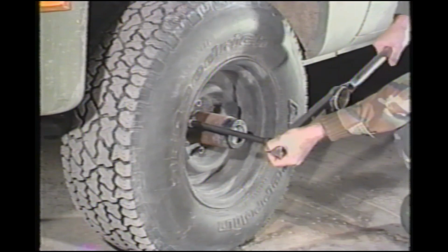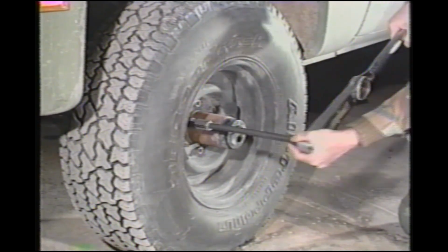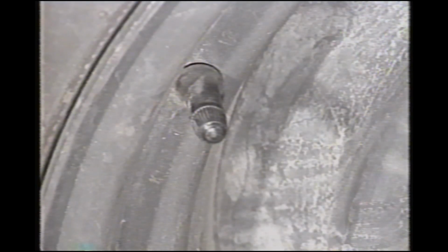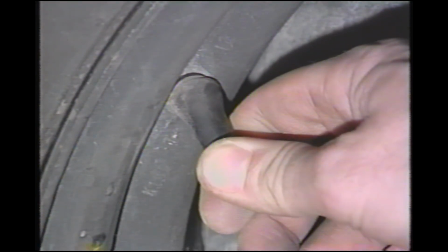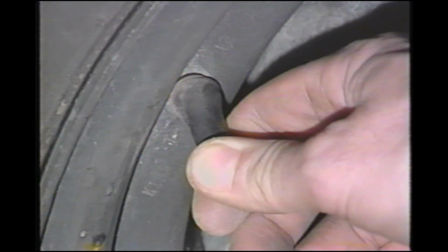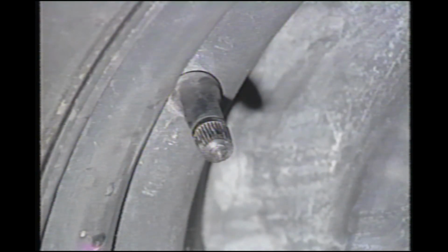Ensure there are no broken wheel mounting studs. Inspect the condition of the valve stem. Damaged valve stems may lead to sudden air loss. If the valve stem has a rubber coating, check it for weather cracking by bending it slightly. If the weather cracking goes to the core, a leak may develop.